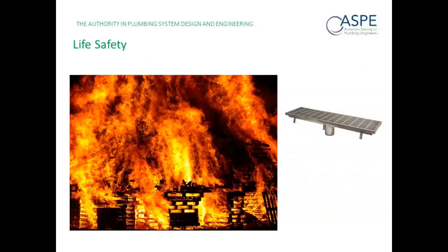So go ahead and talk a little bit about life safety before our next break. Okay, well, we'll talk about life safety. We are all aware that evacuation of a hospital takes longer than evacuation of a traditional building. Same is actually true in marine, but we're not talking about marine today. Again, same issues span various markets. We know that the drainage pipe work, since it's a non-water-filled piping system and passes through different fire compartments, really should have the highest fire rating available.